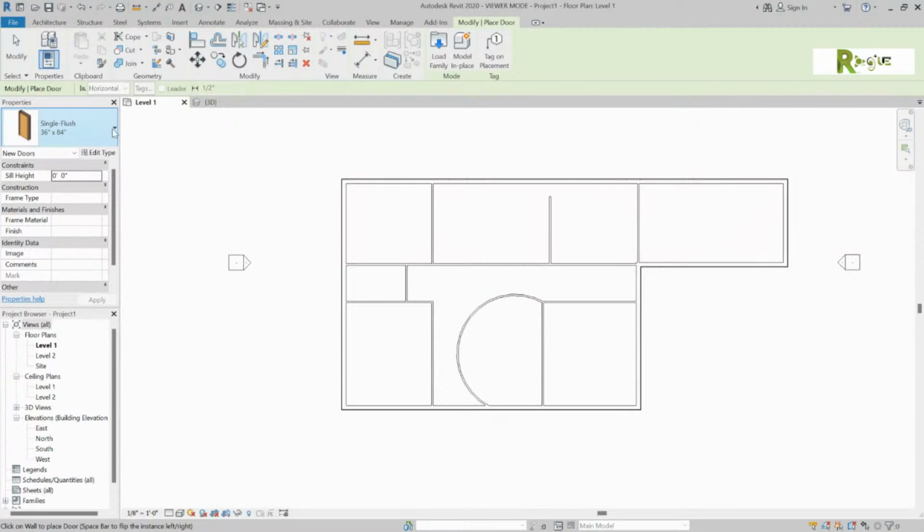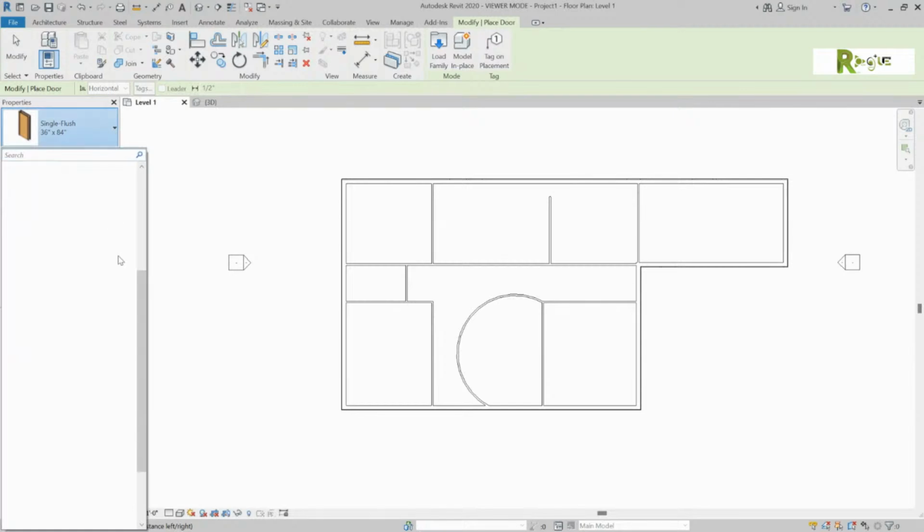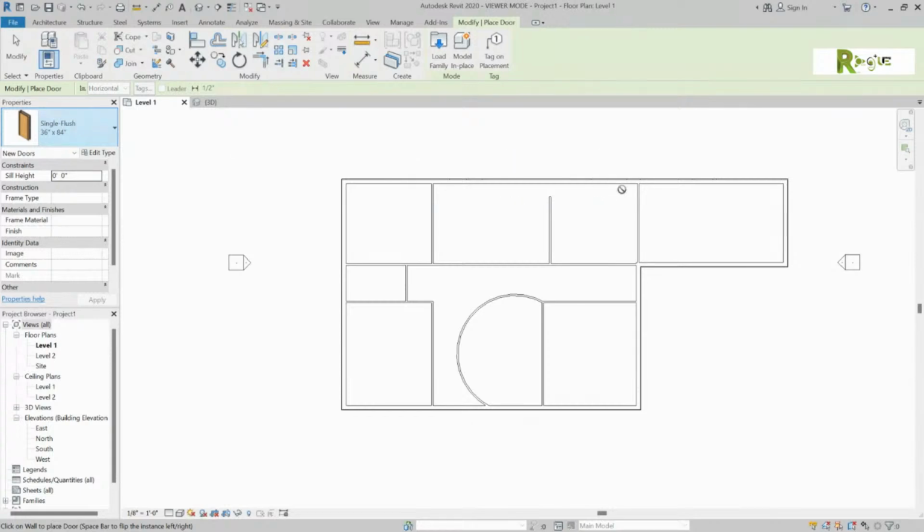We're going to go right across these icons. And that's a perfect thing to do, is to say, wow, it's probably just like the walls, except the difference is a wall is a system family, and this is an independent family. So we can make any kind of door we want. This is where you have to make the family. So all that they've given you is single doors. So we'll put a couple of single doors in. Then we'll show you how you get to a double door.